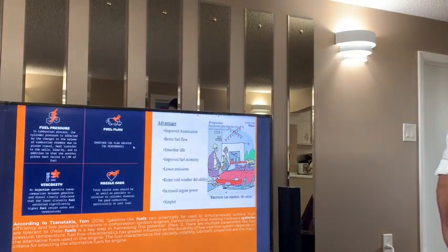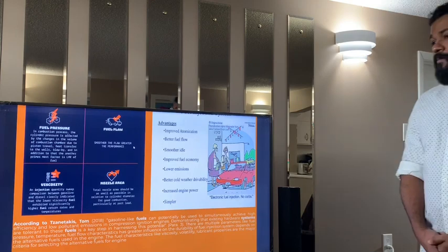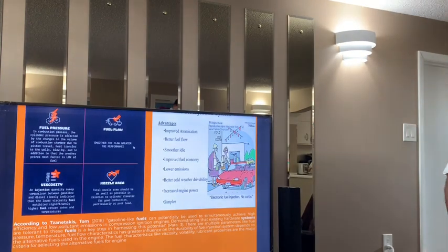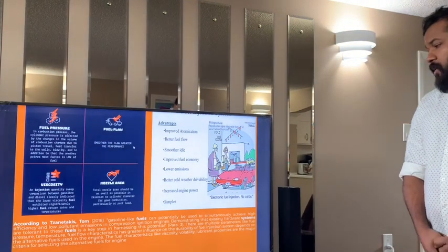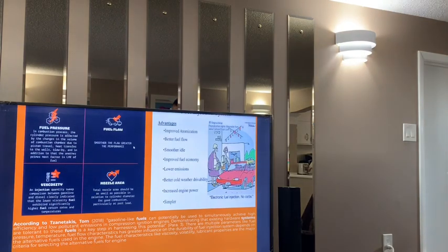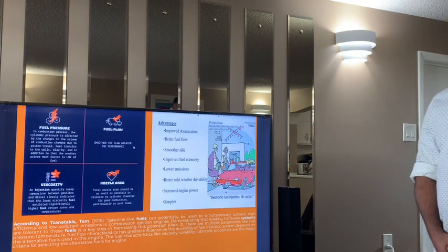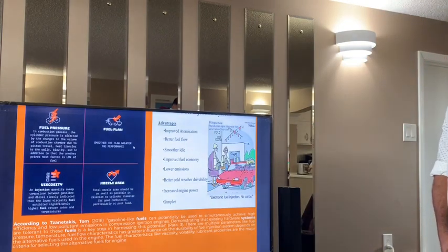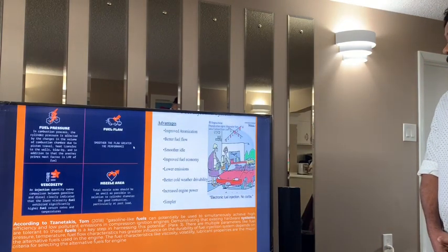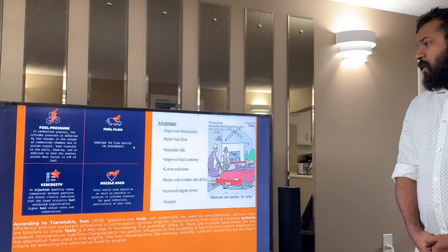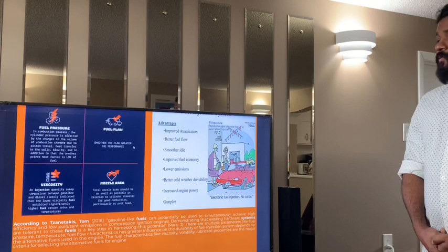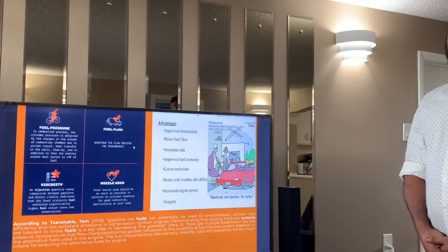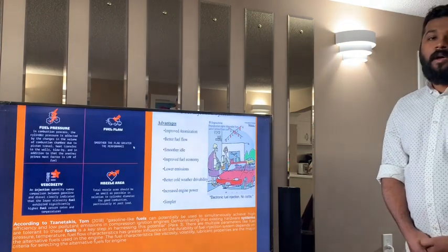There are multiple parameters like fuel pressure, temperature, and fuel flow that have greater influence on the durability of the fuel injection system. It depends on the alternative fuel used in the engine. And also, he said the fuel characteristics like viscosity, volatility, and lubricant properties are the major criteria for selecting the alternative fuels for the engine. So we can easily understand that these four characteristics play an important role in the performance of the fuel injection system.